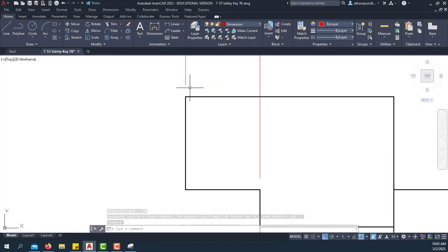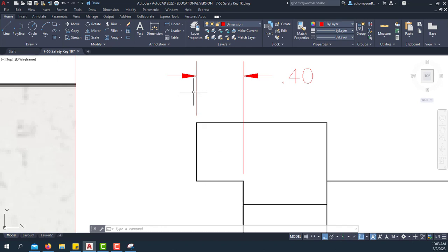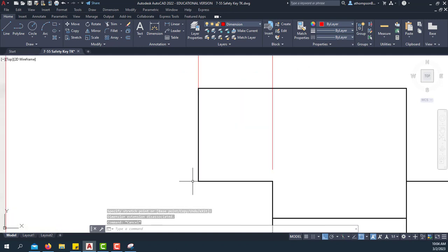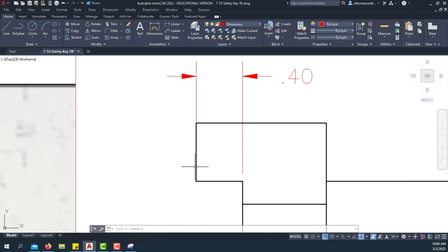And then if I zoom in, you can actually see the gaps. So when you place these dimensions, let's say that you accidentally placed the dimension down here, you know, let's say you clicked on it down here instead of up here. You can see that there's no gap. There's nothing there because my extension line goes over top of my object line. We really don't want that to happen if we can help it. So make sure you're clicking on the outermost line.